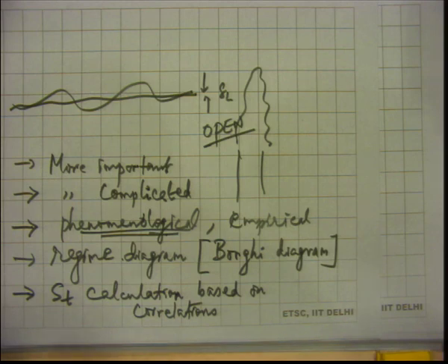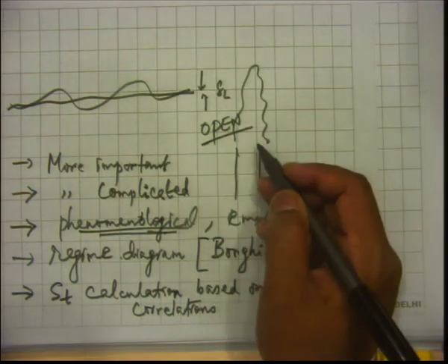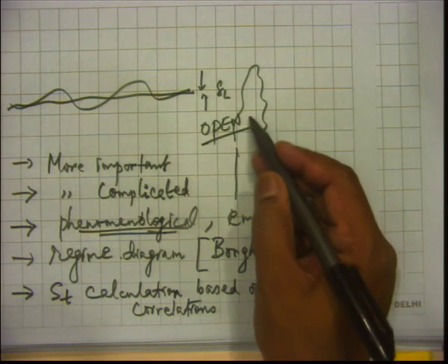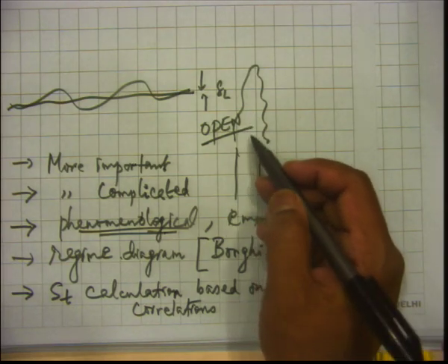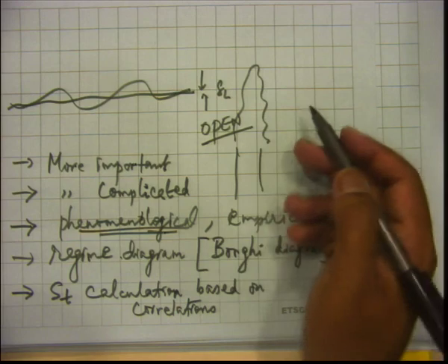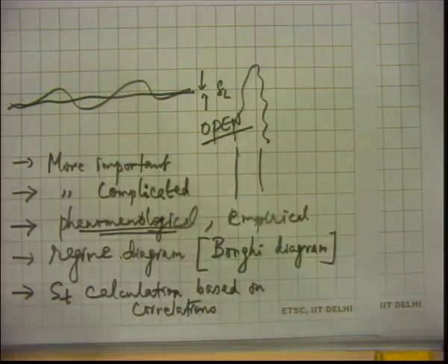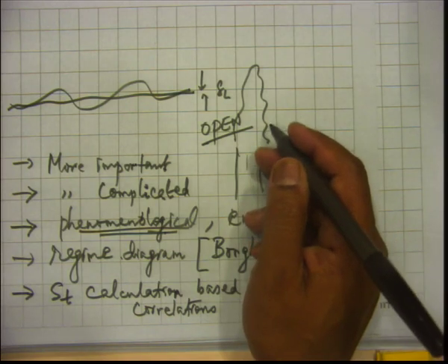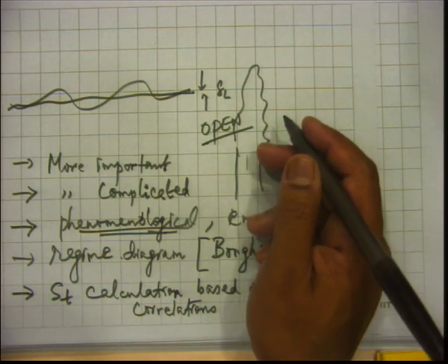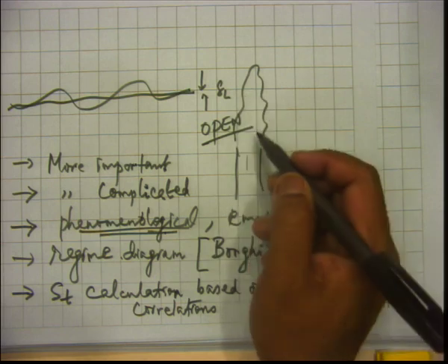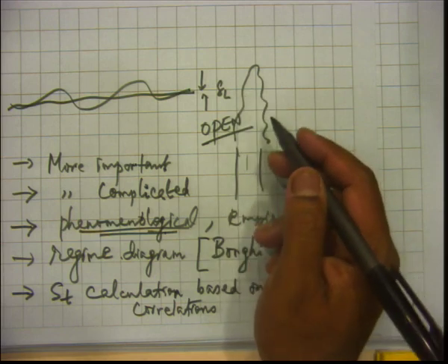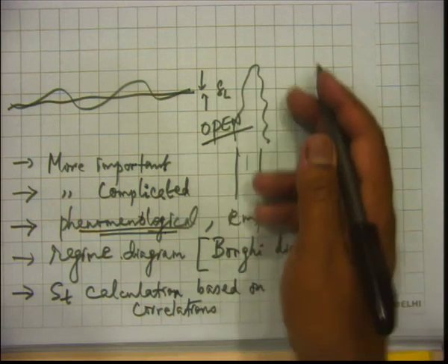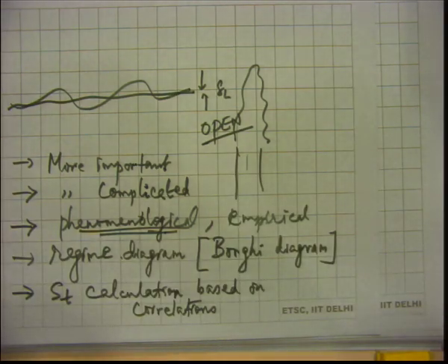So, in an open flame, people have typically seen that the presence of the flame does not change the turbulence parameters of the flow that is coming out from the burner. In other words, suppose you have one situation when there is no flame and there is a mixture coming out from here, you have not ignited. So, it has some turbulence characteristics, length scales, turbulence intensity and all that. If you ignite it, those quantities do not get changed much. Okay. So, that is one piece of information important to remember.